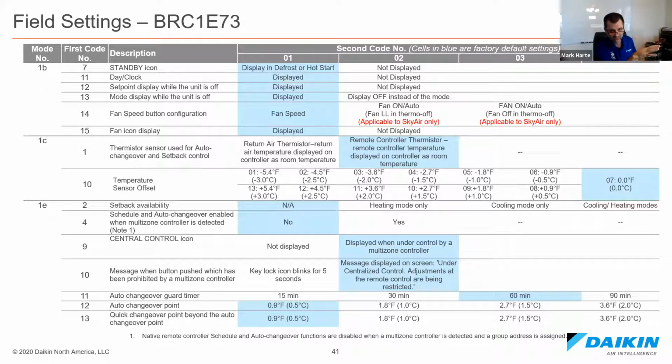So if that fan coil is in air conditioning mode, you can go to that remote controller and look at that liquid line sensor and that gas line sensor, and you can see the superheat of that particular fan coil from the remote controller, because the liquid line sensor is after the expansion valve. It's not before it, it's after it. So we're going to start metering there. So that's going to show us the saturation, liquid and gas going into the fan coil. So it's also a service tool. So there's a lot, but these field settings deal with what you show on the display of the controller.